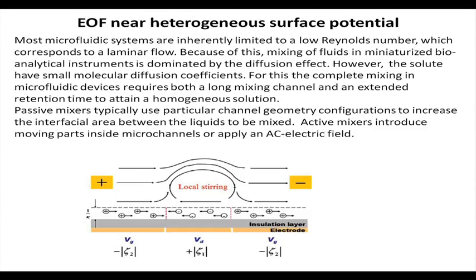We know the direction and magnitude of the electroosmotic flow are governed by the surface zeta potential, or in other words the surface charge density. If you have a different surface charge density, we will have a different form of the EDL, electric double layer, and in that process the flow may not be only in the axial direction or only unidirectional.